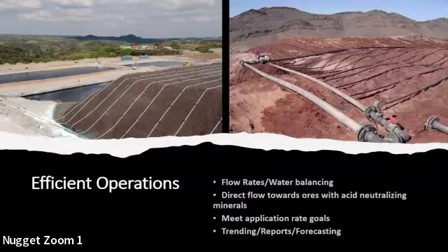So what we see here is the SP ore, the coarser textured ores, which are the red colored here. With depth, we see very little change in saturated hydraulic conductivity. They all remain in that white area, above the 100x safety factor. The argillic ores, which are the more green colored ores here, we see that they do decrease by 1 to 1.5 orders of magnitude over our range of measurement. And depending on which argillic sample we were looking at, around 40 feet to 60 feet below ground surface, it drops below the 100x safety factor.